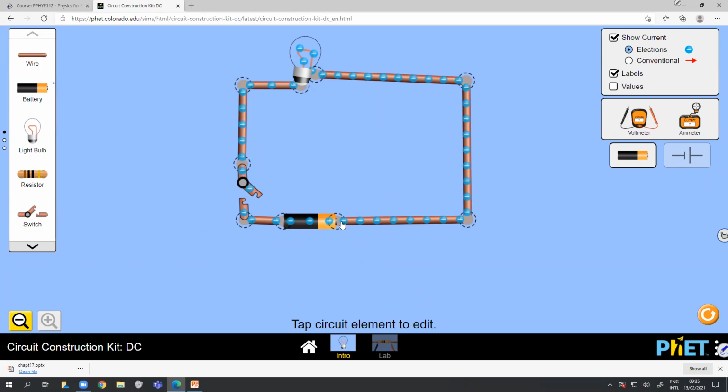Okay, right now it's a very simple circuit. We got a battery and a bulb. So you know, if you connect a battery to a bulb, the bulb will light up. That's because the electrons, charges flow, we have electric current. What is an electric current? Flowing of the charges. So when the charges flow through this bulb, electric current through the tungsten filament inside the bulb, which is under vacuum so it doesn't burn, it will get very hot, red hot and white hot. So that's why we get the light energy coming out.